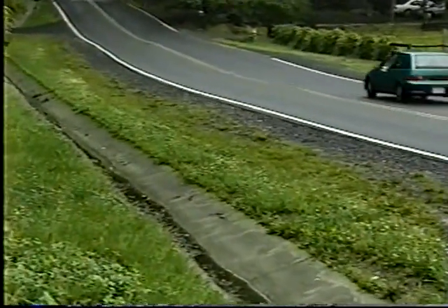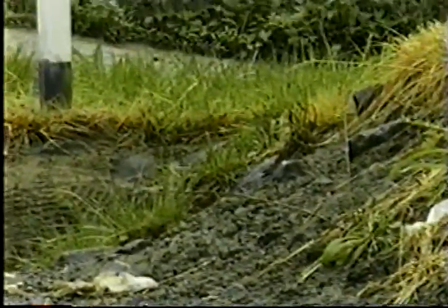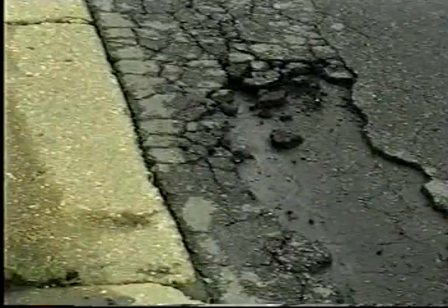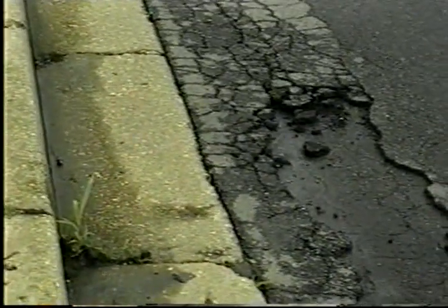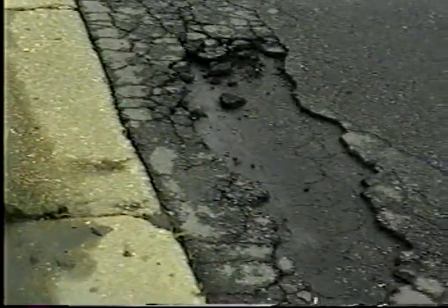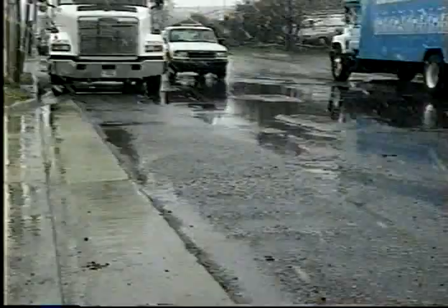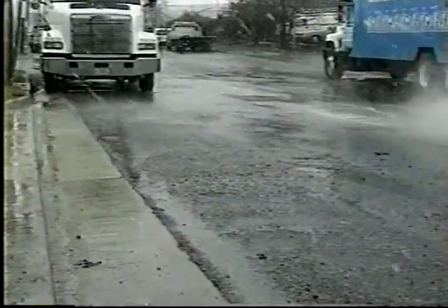Side ditches collect the runoff and convey it to a discharge point, such as a convenient cross drain or an adjacent stream bed. In urban areas, water is contained by curbs and gutters at the road edges to convey the discharge to a drop inlet or a catch basin. If these basic drainage features are not provided, the result can be pavement breakup, potholes, cracking, shoulder disintegration, base saturation, and eventually total pavement failure.